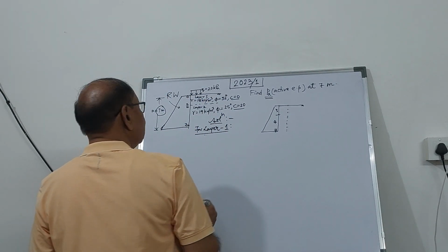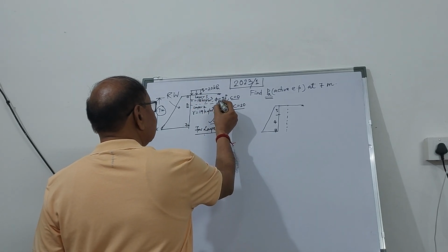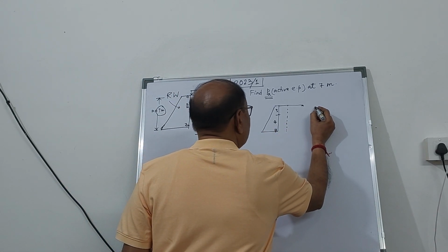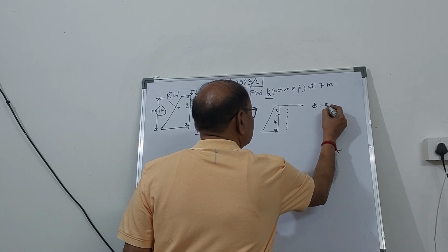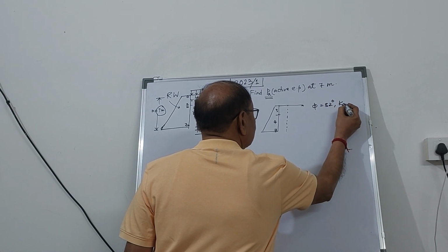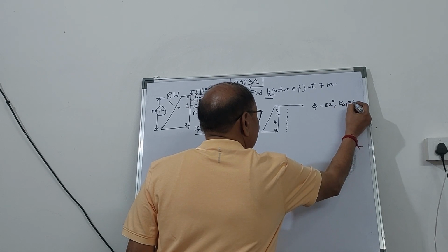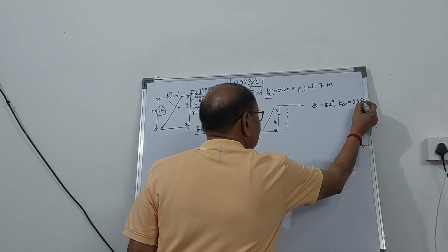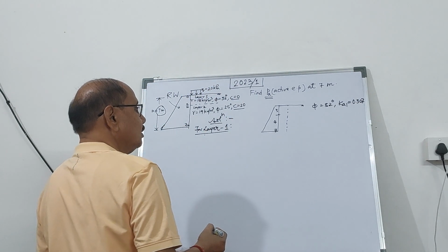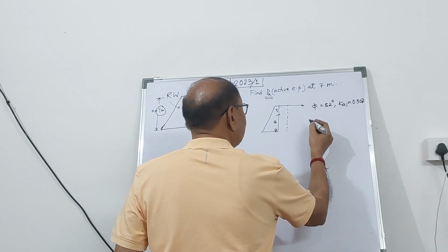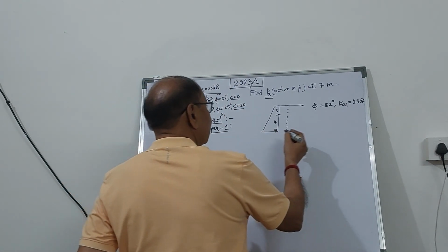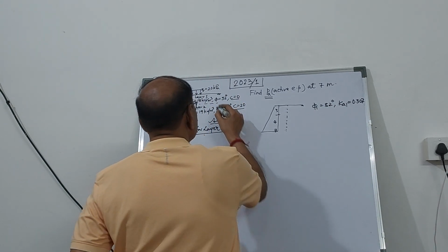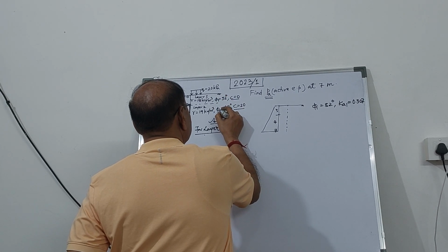You can see that for phi equal to 32 degree, you can find out K1, which will be (1 minus sine phi) upon (1 plus sine phi). So it will be 0.307. So you have got the K1 value. And for layer 2, this is phi 1, and I can call this phi 2.